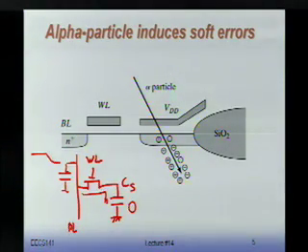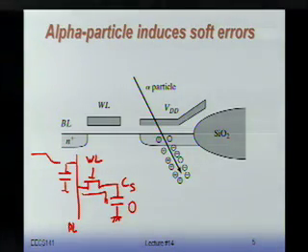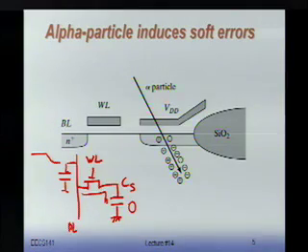Because you have charge redistribution, your voltage is going to drop a little bit, and then I use an amplifier to detect that. Right? It's the basic idea of a DRAM in a nutshell. This obviously is very small. For a single bit, I need 1 transistor and 1 capacitor. Okay? And that's kind of the cell I've drawn here.